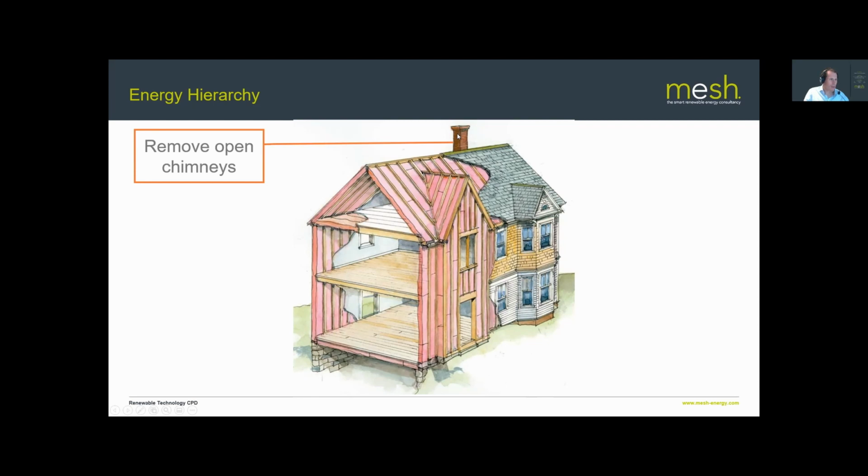Well, first area, we've got an open chimney here. That may well be connected to an existing open fireplace at the bottom in the living room somewhere. Open fires are a real drain on building energy performance. So if you've got an open fire, you have to have a large permanently open air vent. I think it's 5,000 square millimeters off the top of my head. And that has to go into that room. And then a lot of heat is going to escape up that chimney.